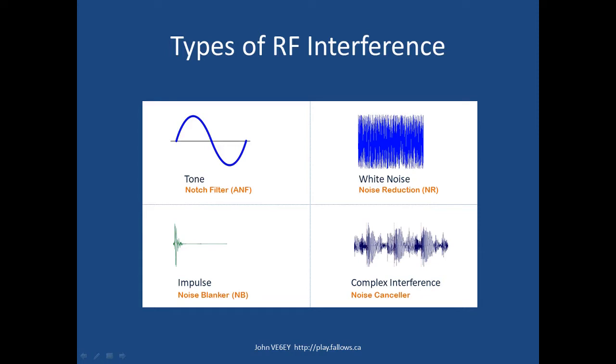It's usually an automatic notch filter. Because all of the parts of this signal are highly correlated, it's a very precise correlation of signal. It's a single frequency. It's very easy to notch that out, and a notch filter can knock it down by 40 to 80 dB. It can just get rid of it. So there's one thing you can do. If you've got a simple tone, you can just get rid of it when it gets into your receiver.